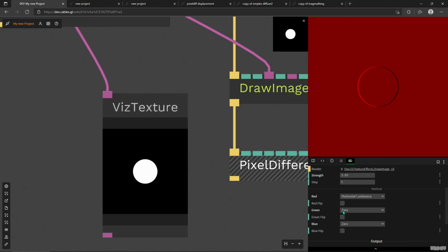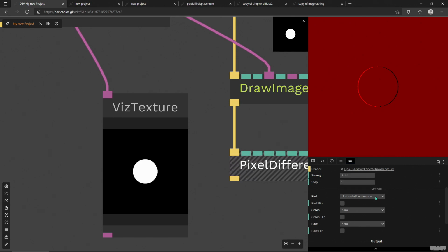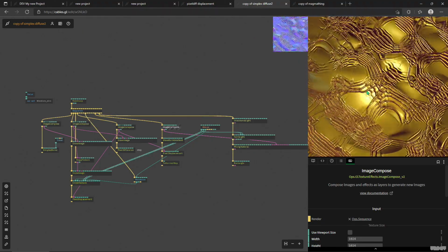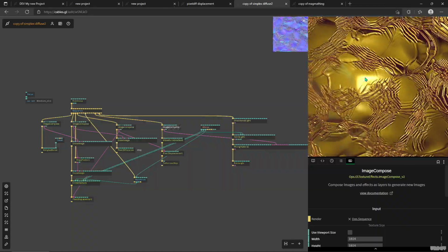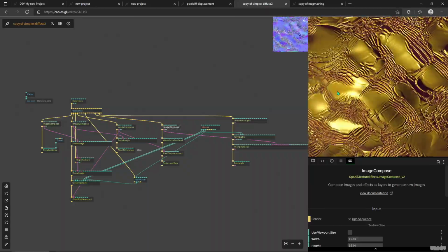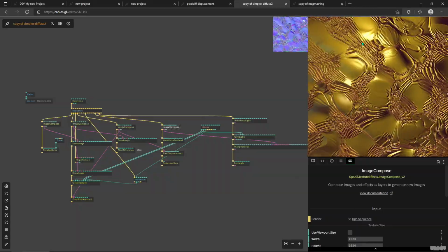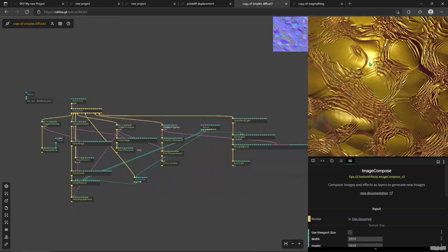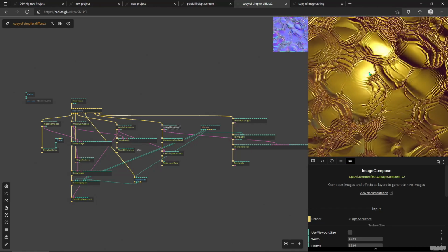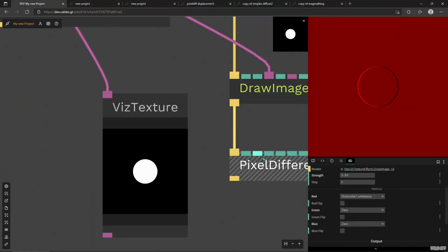And you can get creative, obviously, but if you're going to be doing something super precise with normal maps, like in this example, I think it's a good idea to stay with the standards and put your red channel for the changes in the left right direction, and then set green to the changes in the y direction or up and down. So not a standard you're really required to follow, but I advise it just for the beginning.